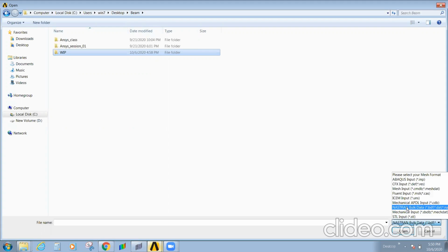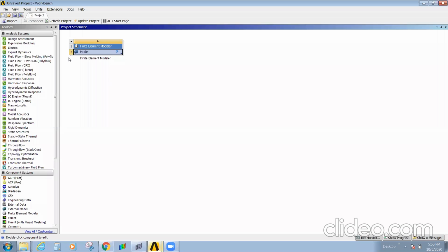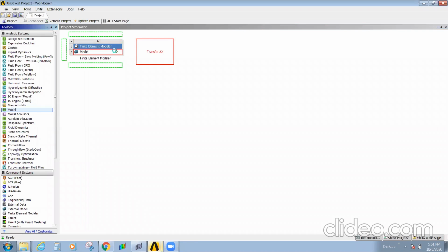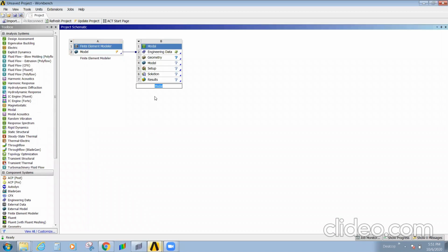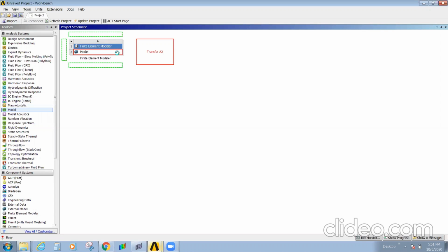So here we'll go for Nastran again. I'm just showing you guys a number of options which will be helpful for you in future. Yeah, so now you can see your mesh has been updated. I'll go with this for modal analysis first. Similarly for here also, the same thing as in the previous one. And first, initially, I'll go for modal analysis.